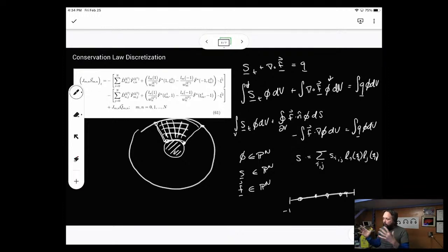Essentially, we're going to map this element to a reference computational space, make all these approximations, and I have basically the Jacobian of the mapping multiplied by the vector of solution variables. And let's see here, so this term, where we're doing f dot grad of the test function, becomes basically a matrix vector product that we can do to calculate the internal contribution to a derivative.